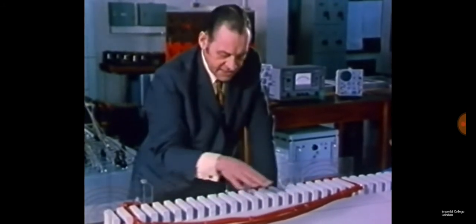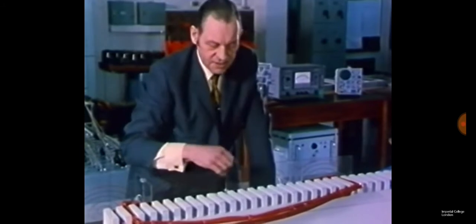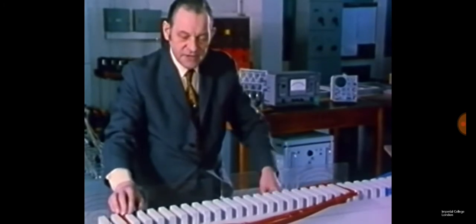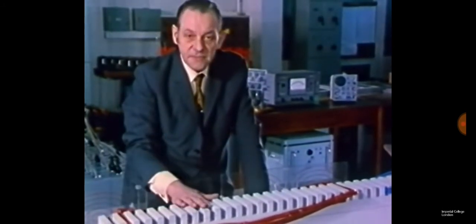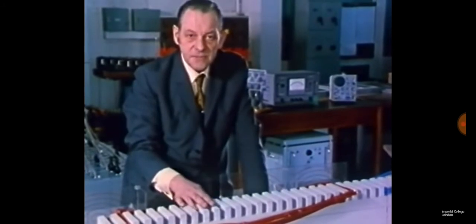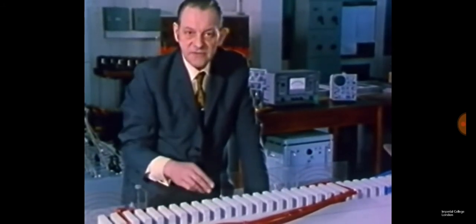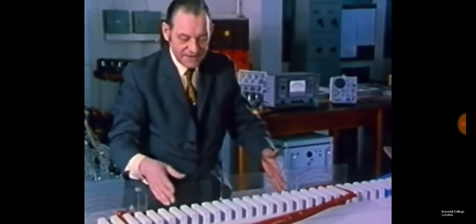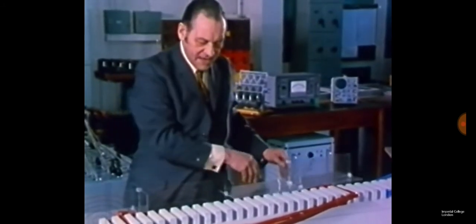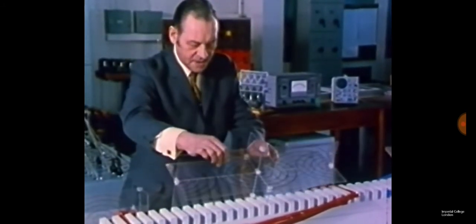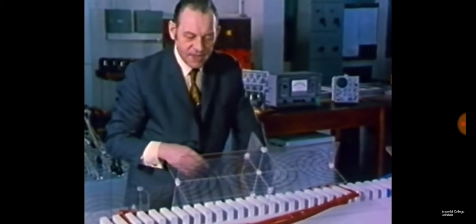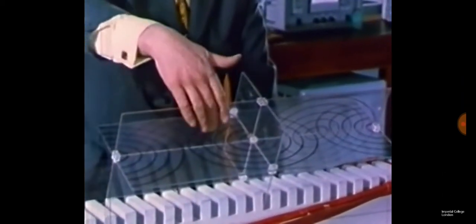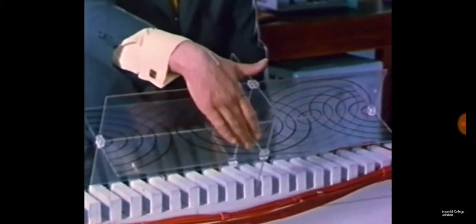Magnetically, all the magnetic flux through these teeth has got to find its way back up the core, and so the core has to be very deep. And so it seemed for a long time as though it was going to be absolutely impossible to design a 250 mile an hour motor to be fed directly from the mains, and yet not to use the mains was going to be very expensive. And then we started to think about shape first and the motor afterwards. And we realized that all the motors we've been making could be represented by a shape model, if you like, of that kind, showing that the magnetic circuits in red are in vertical planes, the electric circuits, or the coils, in horizontal planes, as shown by